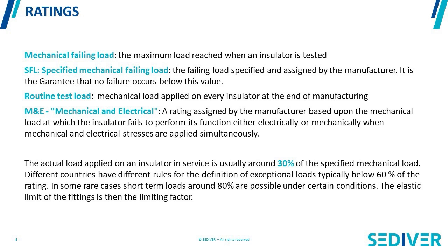So contractually, when we sell insulators, we are bound to the specified mechanical failing load. This is the one you have to verify with the customer to make sure your insulator is what you promise.